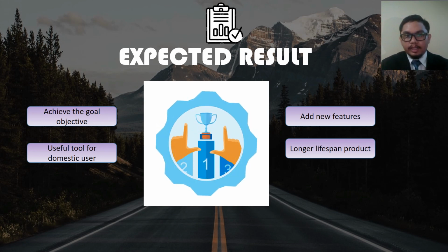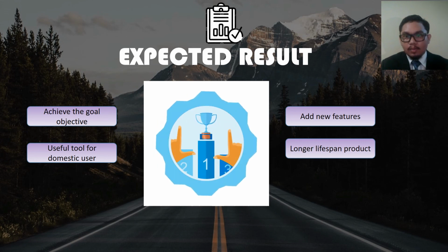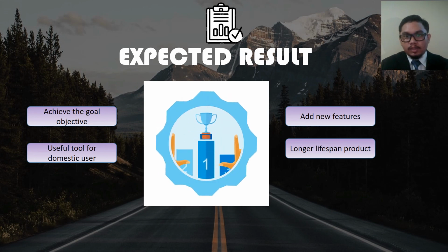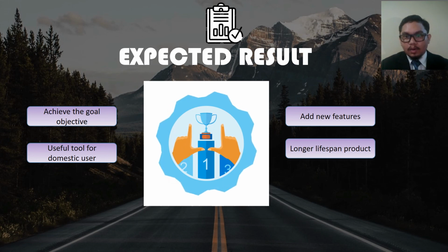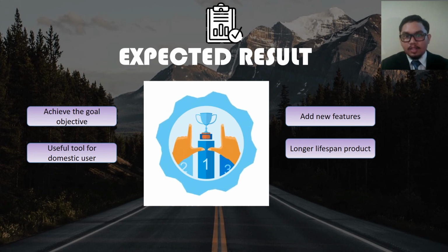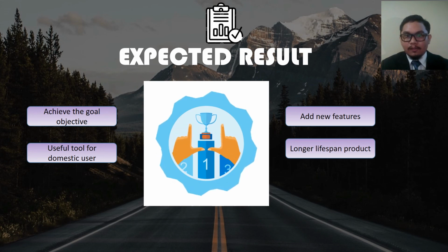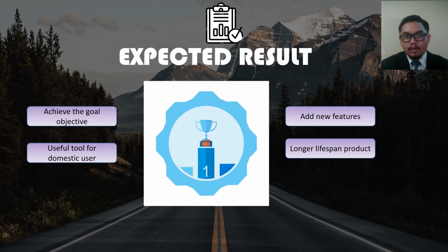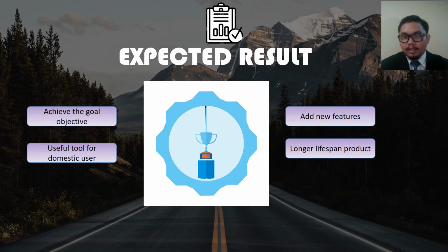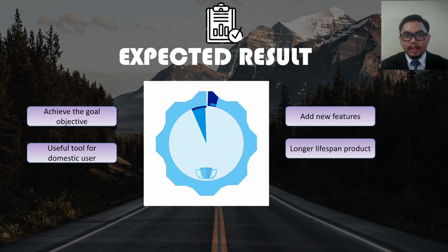With lubrication in cutting, the surface finish of the cut product is better and the tool blade has a longer lifespan. New features like portability, low cost, variable cutting speed and a lubrication system can address the major issues that users face when using a conventional hacksaw, like ease of carrying the machine from one location to another. It can decrease friction while cutting, and the cost is affordable for domestic users to buy.